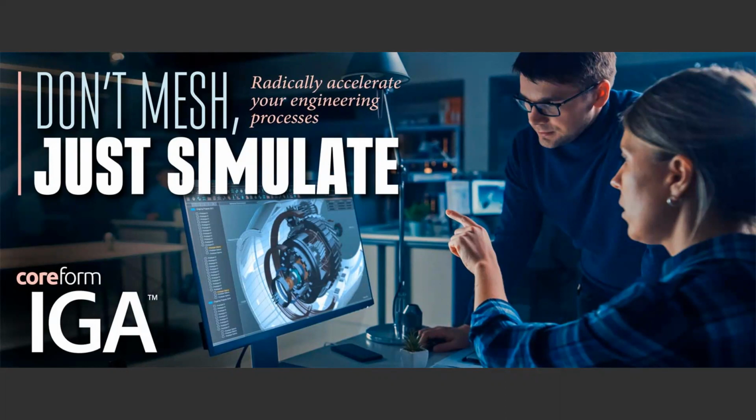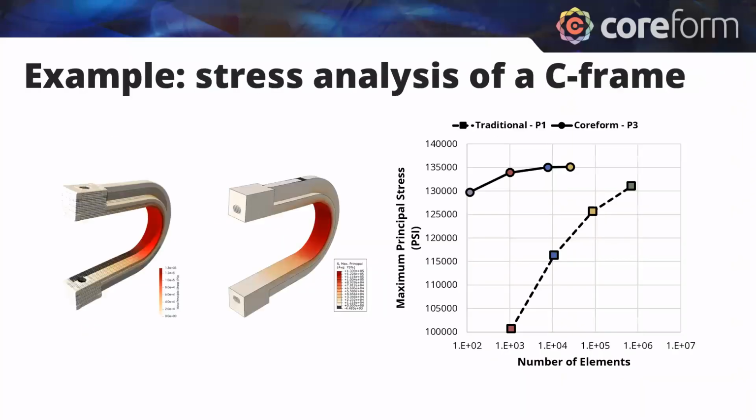However, there are no benchmarks that we can provide you today that literally show that in execution of the code. But we see those things when we look at something like this C-frame analysis: when we look at the linear systems of equations for each of these setups, they're just much more well conditioned. Because we're able to converge with fewer elements, not only are we using smooth, high order elements, but we also have many times fewer degrees of freedom. All those things come together to say that for the same level of accuracy, I think we will be very competitive from a performance standpoint.